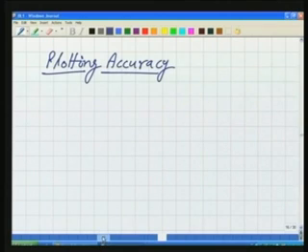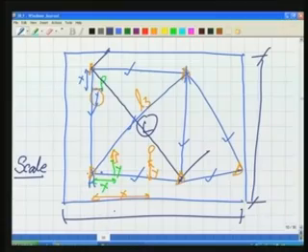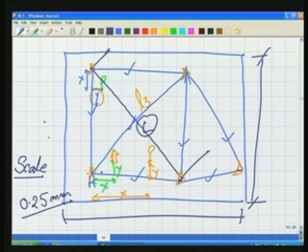In your map, the best that you can plot is, let us say, a dot, and if you are going to be very careful, the size of the dot is 0.25 millimeter. Using the best possible plotting pens, you can draw a dot of 0.25 mm diameter, or we can say for a line, the thickness of the line is 0.25 mm. What is the meaning of this? Does it convey anything? Yes.